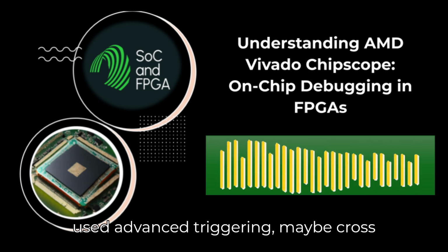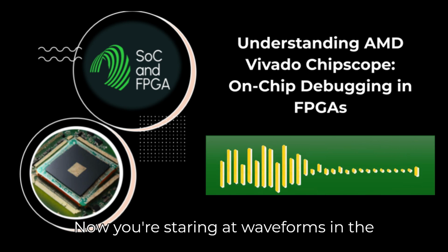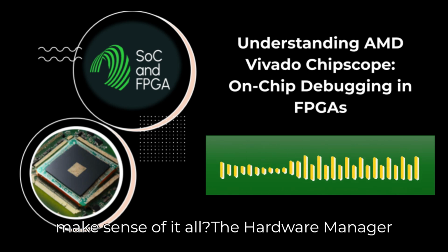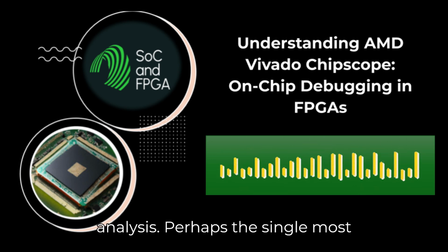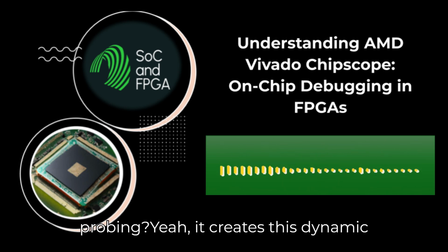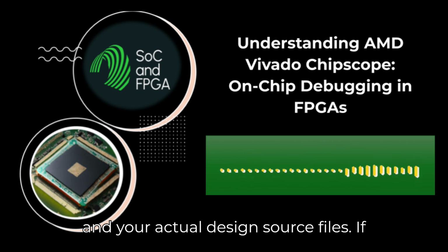Okay, so you've used advanced triggering, maybe cross-triggering, and you've captured the data. Now you're staring at waveforms in the Vivado Hardware Manager. What helps you make sense of it all? The Hardware Manager GUI has several key features for analysis. Perhaps the single most powerful one is cross-probing. Cross-probing? Yeah, it creates this dynamic link between the captured waveform data and your actual design source files.